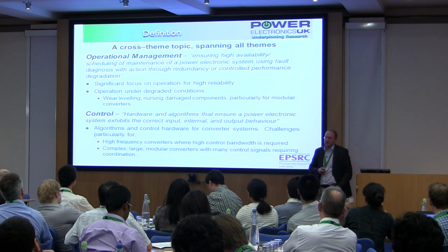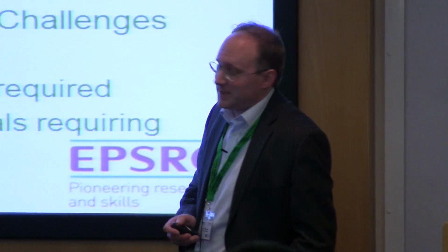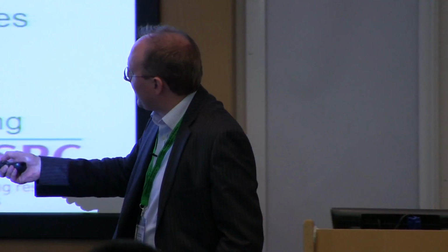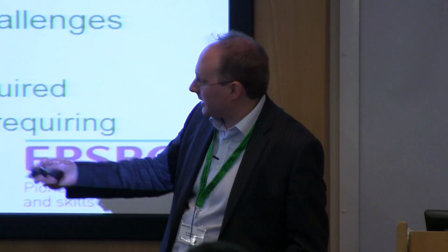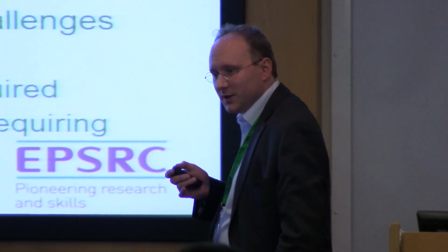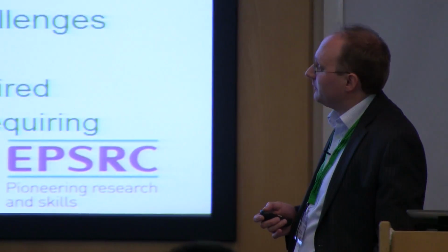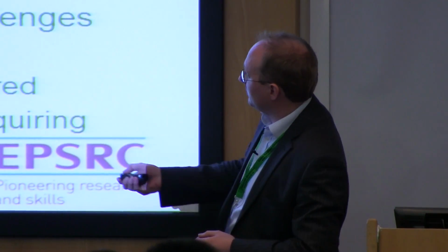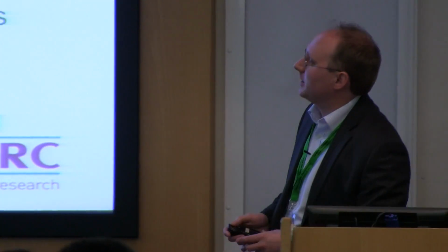And all of that leads us to needing higher and higher control bandwidths. So there's clearly a challenge as we go to higher frequency in terms of having the necessary high control bandwidth on our control system. The other challenge that comes about really is due to large, complex converters, particularly modular type grid scale converters, where you have a terrific number of devices and therefore a terrific number of gate drive signals, and also potentially a huge number of variables that you want to monitor and pass back into the control system. So there's just a large size-based complexity issue with certain types of converters. So that's the sort of stuff you might understand typically by normal control of power electronics.